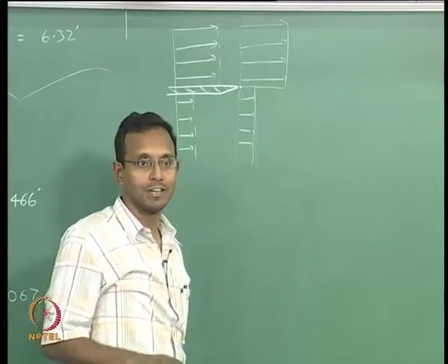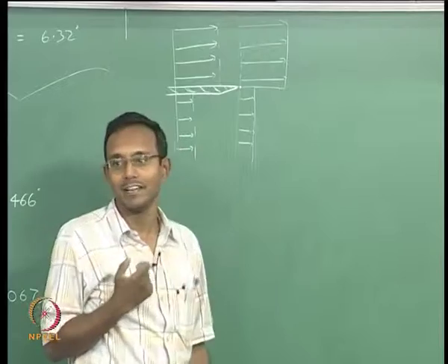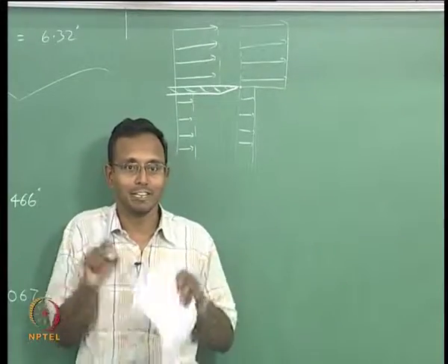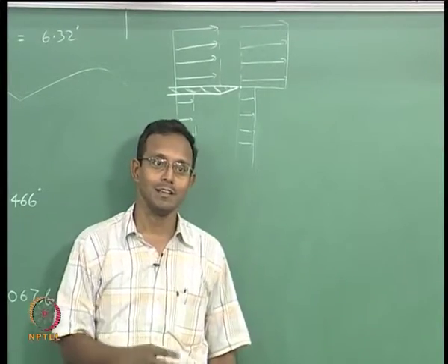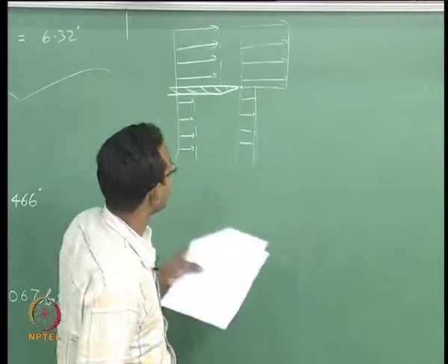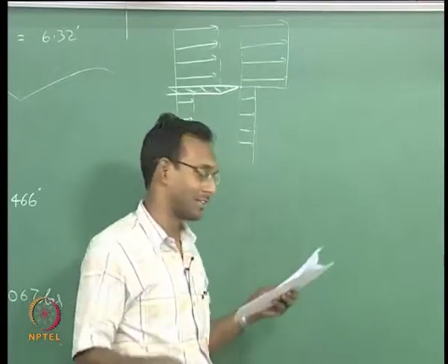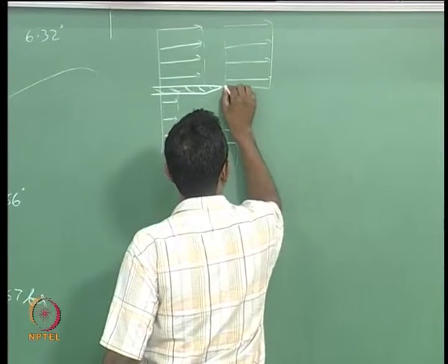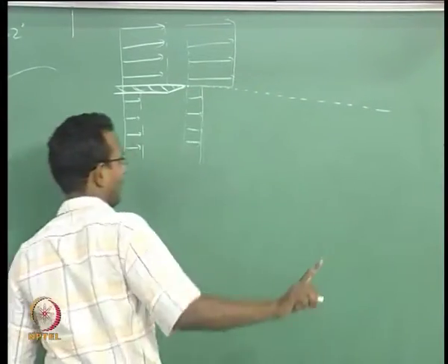Every other place it is 0, only one guy has all the vorticity, and viscosity does not like it. So it will take it from that person and give it to the immediate next person, and it diffuses out from there, and everybody eventually has the same amount of vorticity. If there are so many fluid elements, they will all have almost 0 vorticity. Now, some distance downstream, I will draw a dotted line going slightly downward, we will come back to that later.